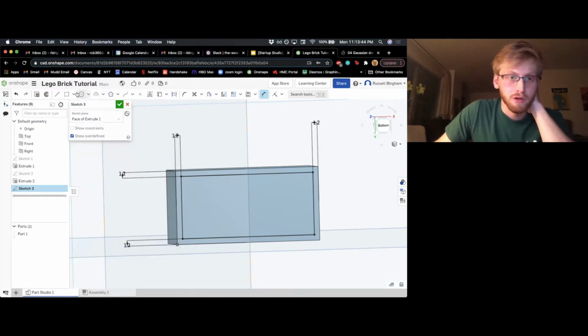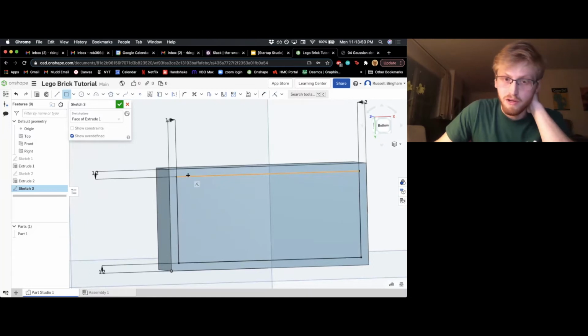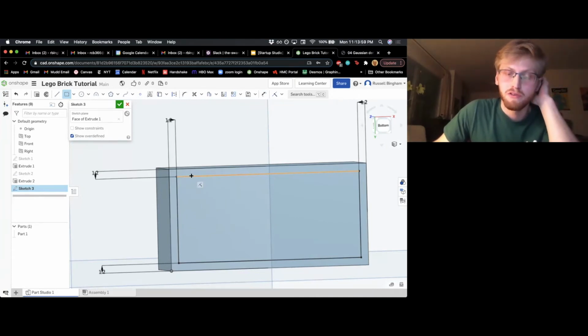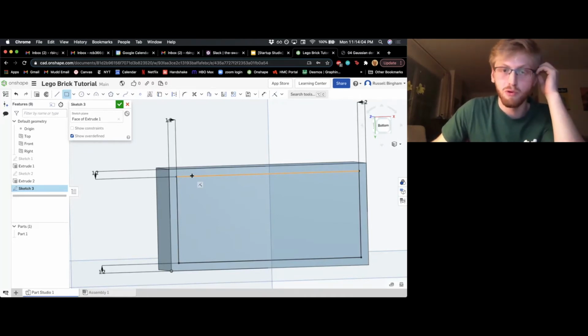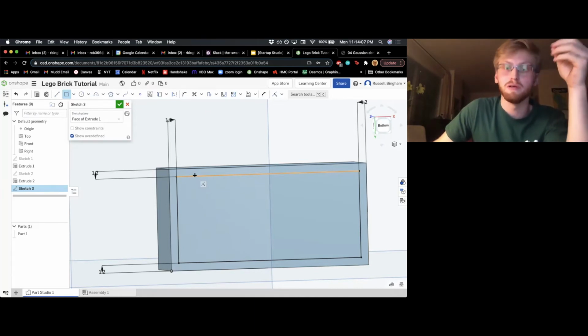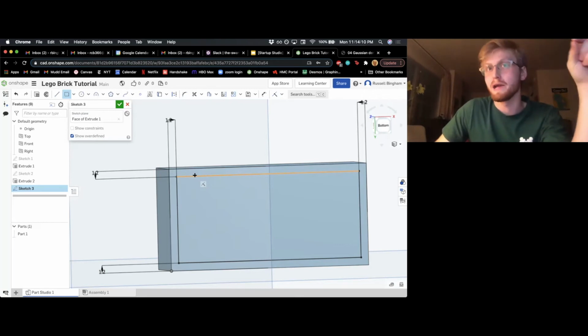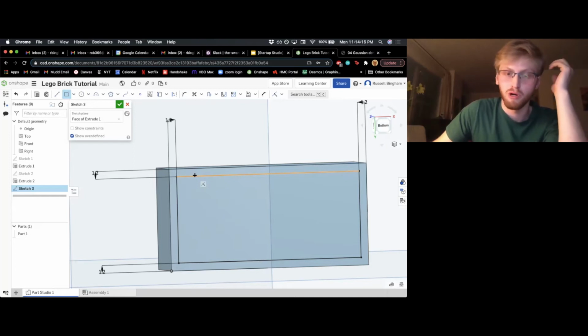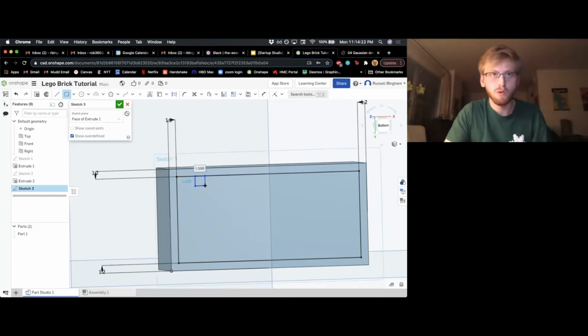So I'm going to go here, and we're going to hover along this line here, and you'll see that little icon there, the 2 perpendicular lines. That indicates a constraint. When you click here, this is called a coincident constraint, which means the point you click on is going to be forced to remain on this line. Basically, it's not going to float away from that. That becomes more relevant with more complex geometry, but this is an example of a constraint. So rectangle, we want this to be 0.6 wide and 0.3 tall.